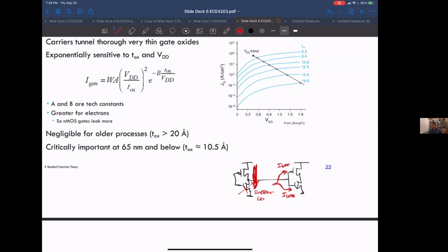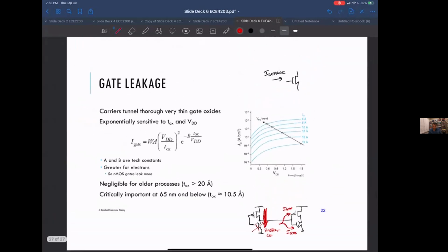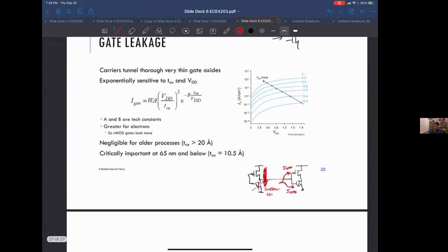So typically the gate leakage is significantly less than the subthreshold leakage, and you don't really care about it except when these gates get very large. There are a few circuits that are too complicated to get into right now. I don't know if you've heard about phase lock loops on chip to generate clocks.